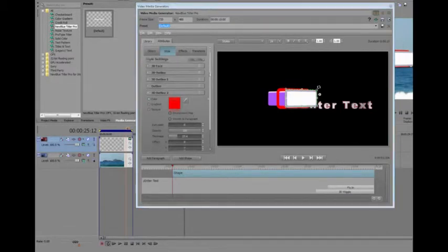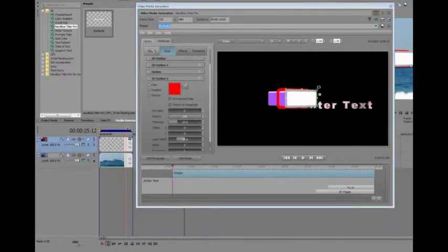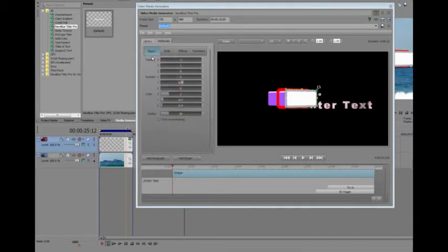The checkbox to turn keyframing on is in the Objects area of the Attributes tab. So click the Objects area, and then you've got all the object controls, and there's the checkbox for turning keyframing on. Just click it to select it, and now you can add new keyframes, change your position here, add a new keyframe, switch back and forth between the keyframes that you want to use, and so forth. So just select the Turn On Keyframing checkbox.